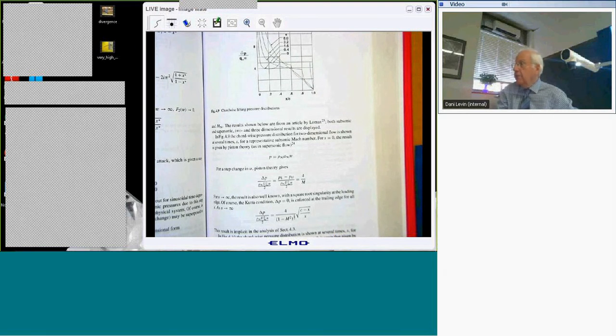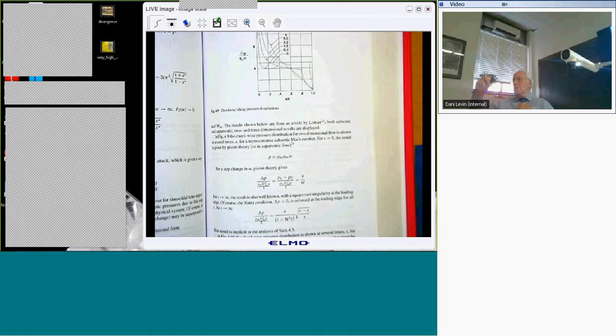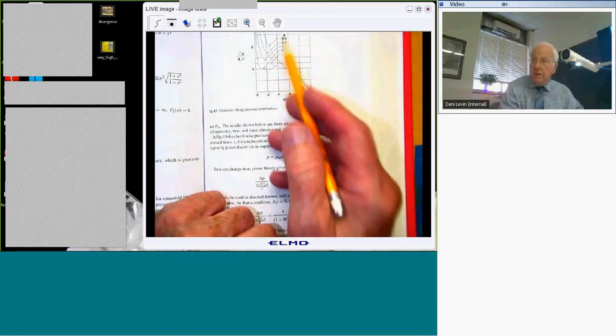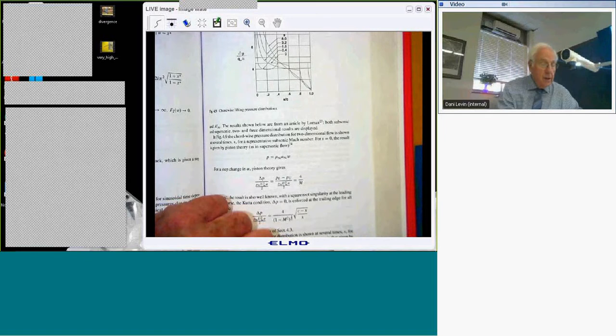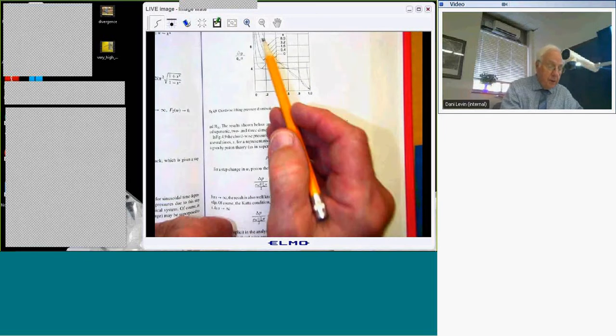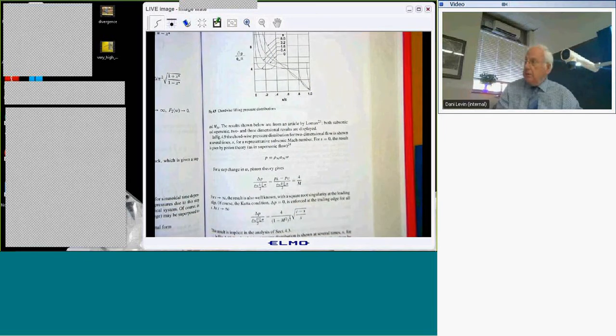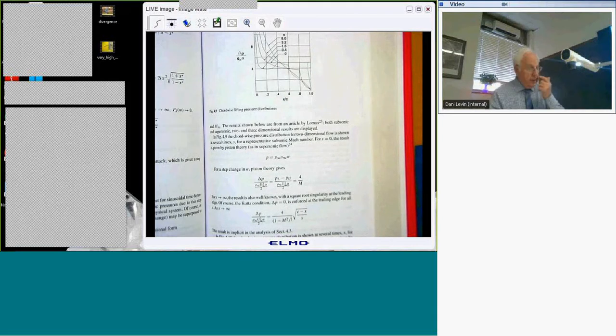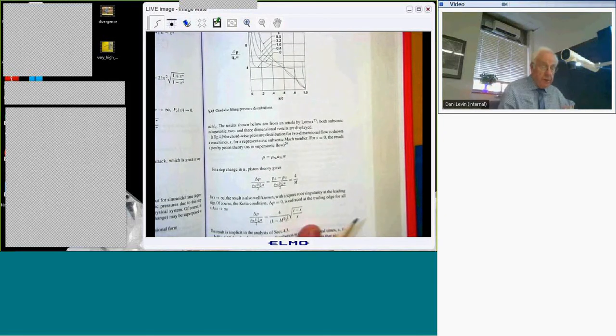Isn't that nice? And that value is pretty close to what you measure in a wind tunnel. It's a little high. Because of viscosity effects and because of finite thickness of the airfoil, it's usually a little less than what this formula would provide by way of lift. It's a pretty good approximation. Okay, and then in between, various other things. It's complicated, right? As time evolves, it goes from this uniform result to this result as time moves on.